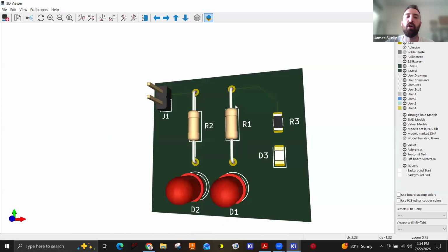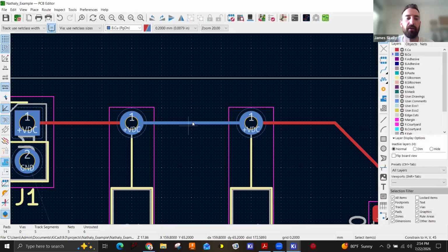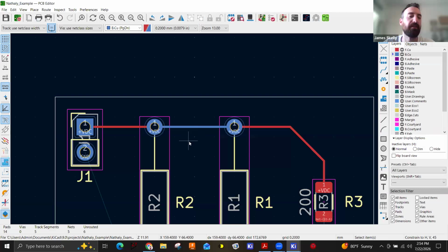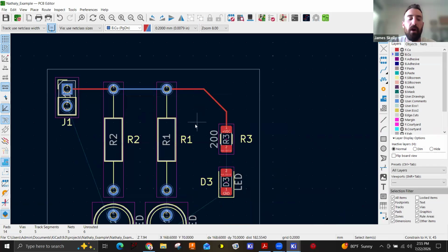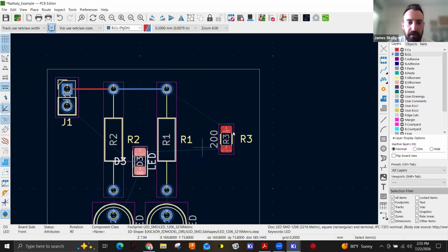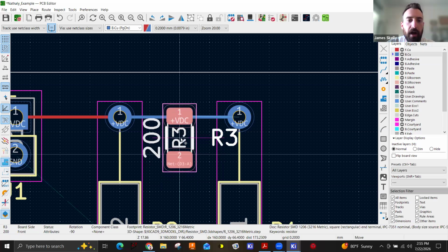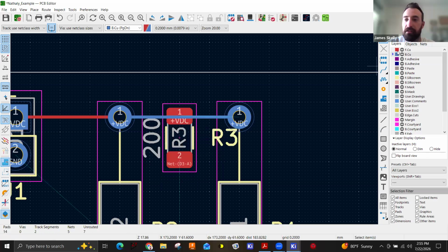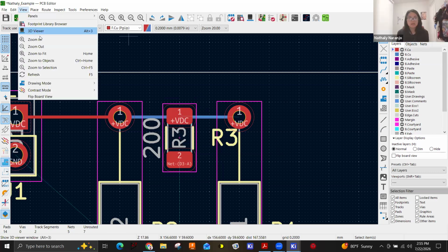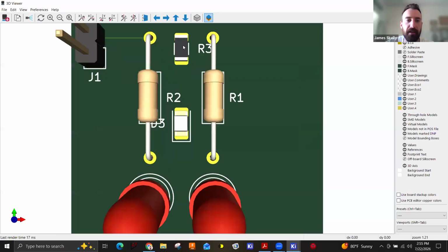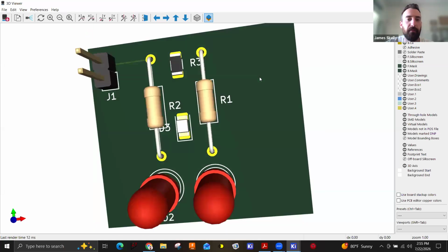So that can be just personal preference, but it's also, let's say you wanted to put another component here. You could put a component here now. This is where using surface mount components becomes really, really valuable. If I wanted, let me erase this trace. I could put my surface mount components in the middle here, and I could just put this right on top. And there's no problem with that because on the bottom layer, that blue is not doing anything to this resistor, right? If I look at this, my resistor is sitting there completely isolated from what's going on the bottom of the board.